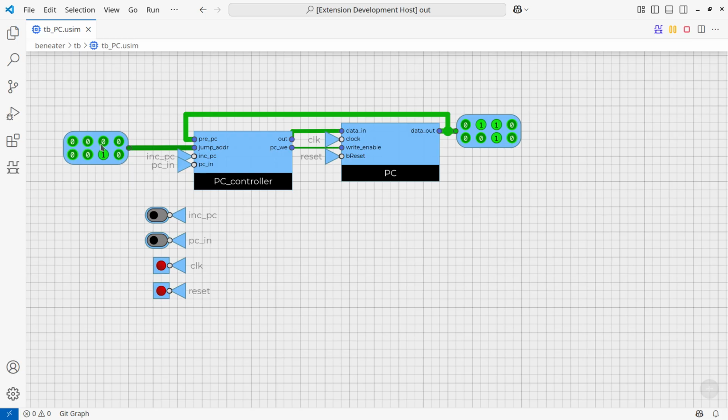So for example, when I changed this opcode, nothing was happening, normal. Let me do a reset and enforce these values. So let me increase, let me clock. Great, now it's increasing. Now instead of increasing, I would like to do a PC in. I have put a PC in. Great, let me change this, PC in, remove these values, clock, and now instead of having this, we have an increase, and we are increasing. As you can see, we overflow at 4 bits. Great.